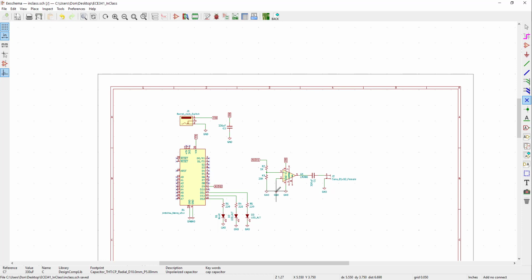This LM386 chip could be a surface mount or a through-hole. Those parts could also be different versions of through-holes or different versions of surface mount. For example, the resistor comes in very small parts like an 0402 surface mount to very large parts like a 3-watt through-hole resistor. Anything in that range could be what I put onto the layout.